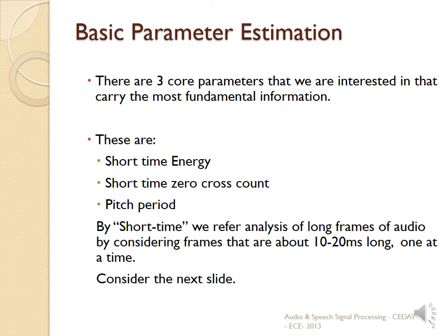10 to 20 milliseconds is not an arbitrary value. This is roughly the order of magnitude that it takes the vocal cords to vibrate. Okay, it's probably around 50 to 100 hertz. So this is why we select such a time. We are going to look at each of these independently.